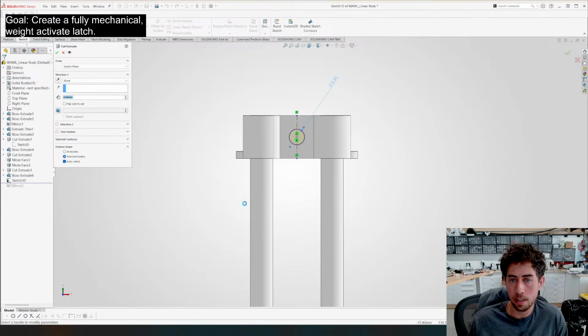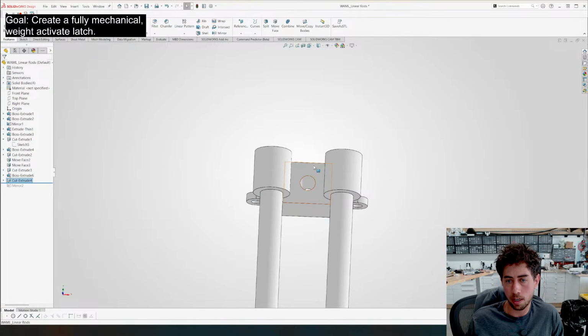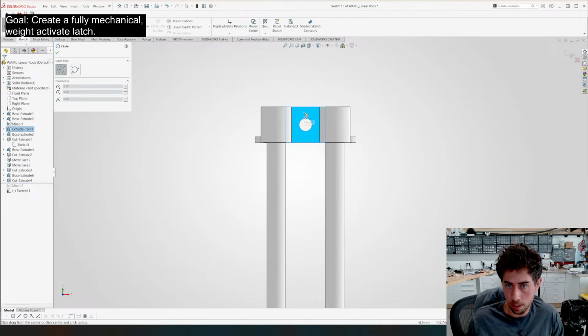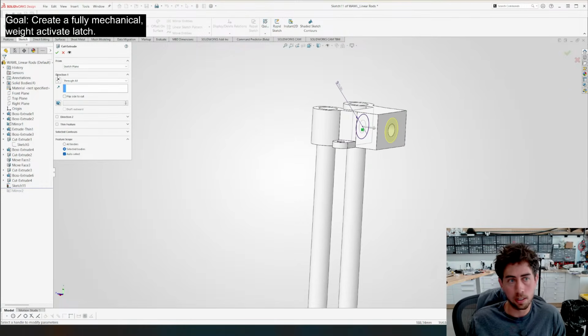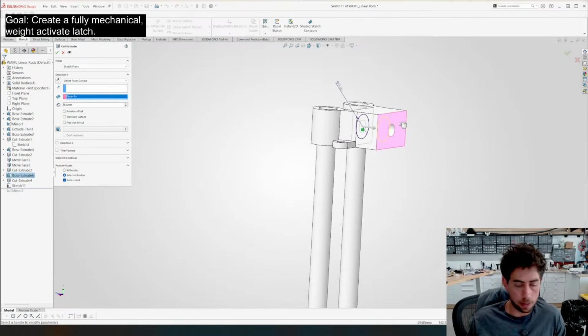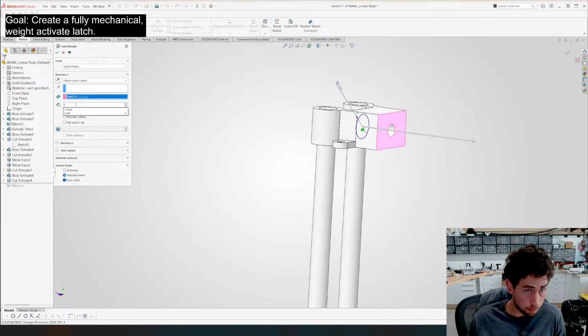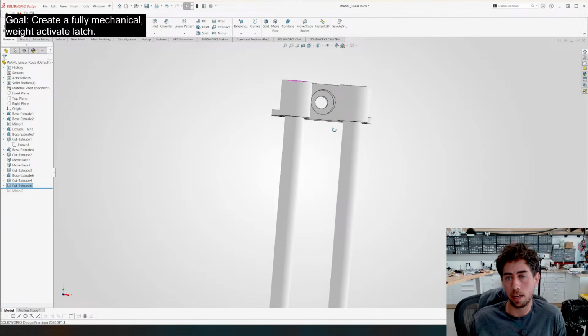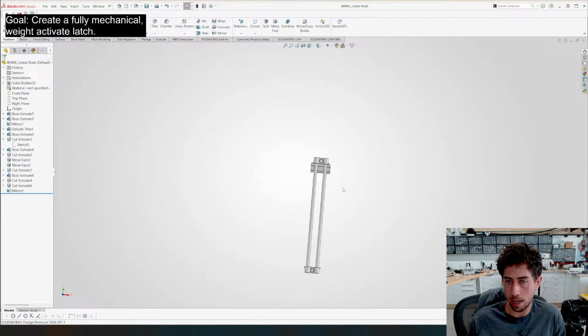5.5 cut through all. And then another one for the screw head counterbore. And that I normally make 10.5. Boom, cut. Offset from this surface 5. Boom. Okay, so now we got our screw. There we go. It's perfect. Boom. Got that. That's ready to go.